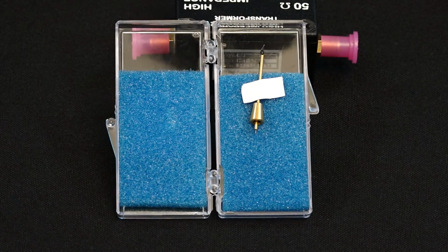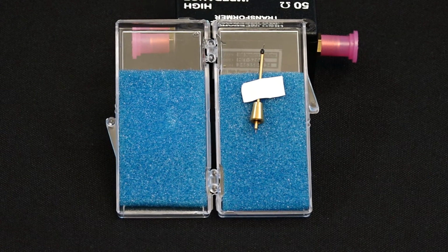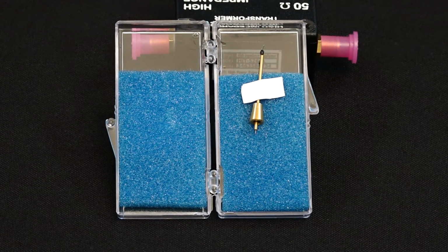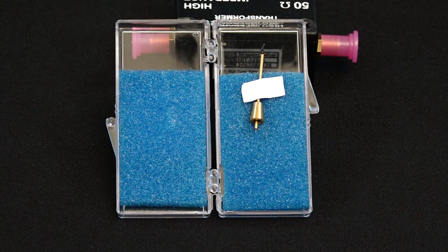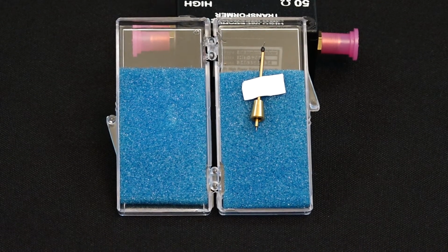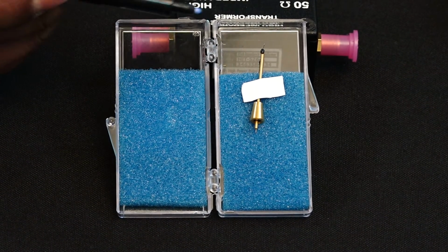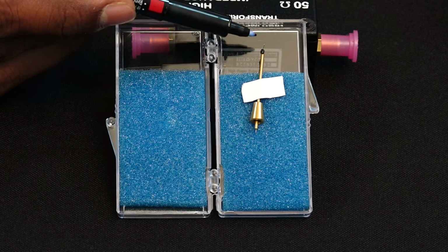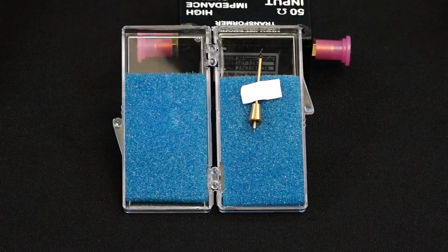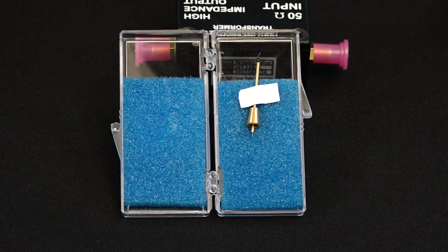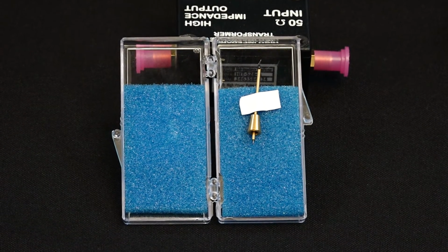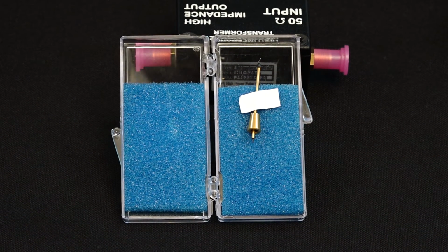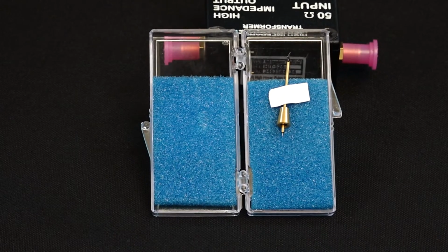The next component that I'm showing you here is a probe tip. When you have the whole setup in place and your device is ready to measure, the connection to the device is done through a set of probe tips. These probe tips are electrical conductors. You can see a couple of thin signal wires here. As I told you, TLP in itself is a 4 probe measurement, so it will involve 2 sets of probes at both the contacts, source and drain, or any set of contacts that you want to use.